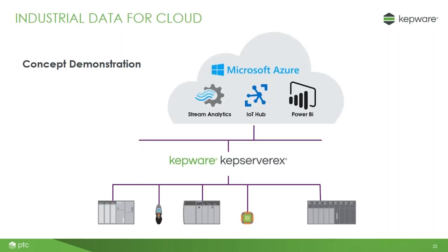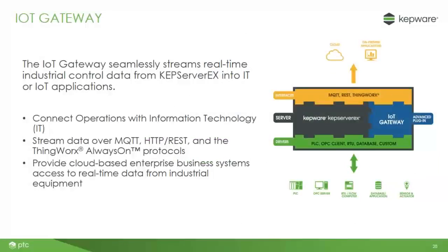And then we have a big layer on top that provides server interfaces or publishing kinds of interfaces to move that data that we're collecting out of KepServer. And then in the middle is a layer of normalization, where when we get a tag object from, say, on the left from a PLC, the protocol that delivered that data might be entirely different than the protocol that delivered the sensor and actuator data all the way on the right side. But by the time the drivers hand the data to KepServer's server interface, it's normalized. It's modeled, you could say, in the same way, where we have an object called a tag and a value property and a timestamp property and a quality property that reflects our success or failure in obtaining that data the last time we tried. So that object is normalized. By the time the data from all this different technology gets into KepServer, it all looks and feels the same and lets you work with it really simply.